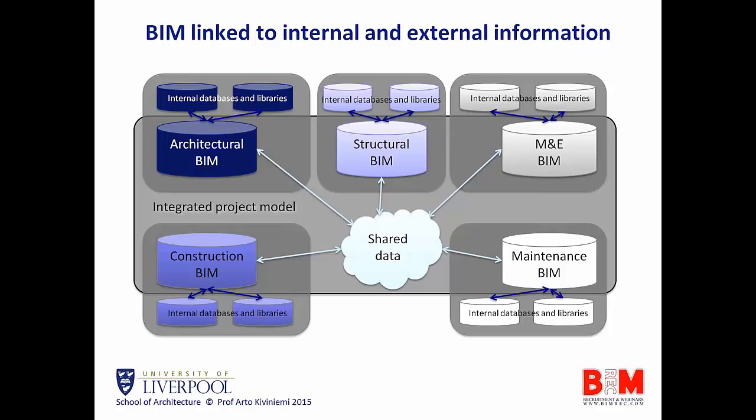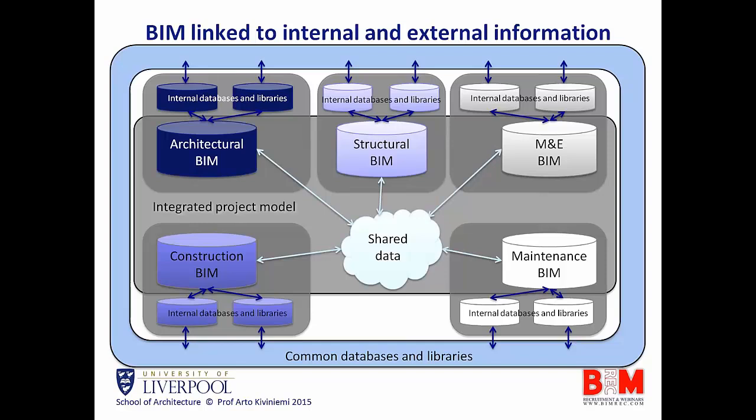But if you start embedding the cost information on the project level, it's very difficult to maintain when the prices are changing, for example material prices or labor prices, because you have to remember to update that everywhere. And that's not the way that we should work in the BIM environment, where one of the central principles is that one piece of information is stored in one place and then linked to the other places where we need that information.